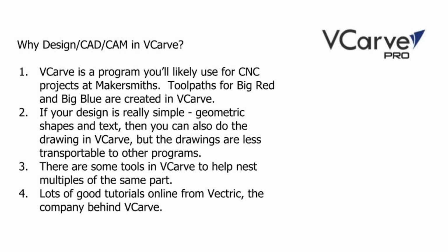In terms of using VCarve for your CAD work, your design work, it is quite limited compared to Inkscape and Fusion 360. If your design is very simple with basic geometric shapes and text, then you can certainly do your design work in VCarve, but anything more complex, and it makes sense to learn one of the other programs first. There are also some good tools built into VCarve for nesting multiple parts to use the least material, and those functions are not in those other programs. And Vectric, the company that makes VCarve, does post a lot of skill and project tutorial videos on their YouTube channel that are worth checking out.